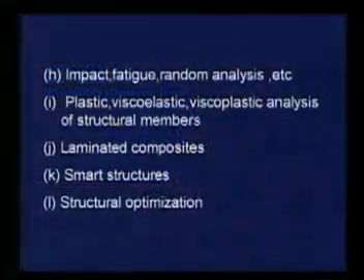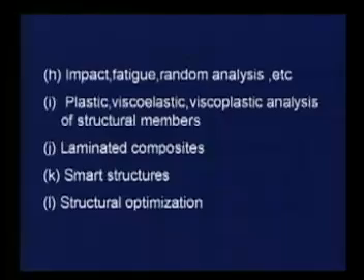We know that most of the materials that we have do not have one predictable material property because of manufacturing defects, because of where I am getting the raw material from, what is the raw material. So a random analysis is often very useful. Also the effect of changing loads, changing geometries, everything can be incorporated, and for that also we can use finite element methods, and we have a special branch there called the stochastic finite element methods.